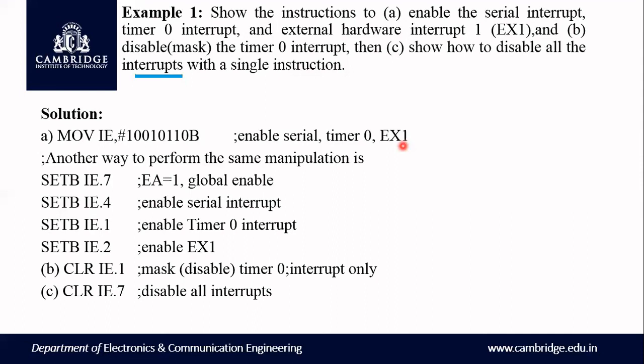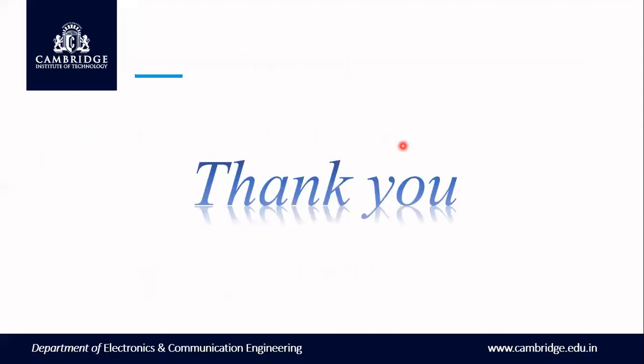So this is the basics about 8051 interrupts. There are a total of five interrupts, and two methods: interrupts and polling. In the polling method, it continuously monitors the devices and serves device by device. Interrupts have more advantages. If you want to accept or disable interrupts, you can do that through the IE register. We also learned the total number of interrupts, the interrupt vector table, and how to enable the interrupt. These things we have learned in this particular video.